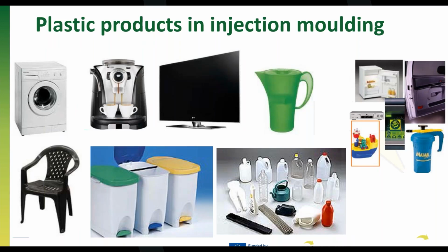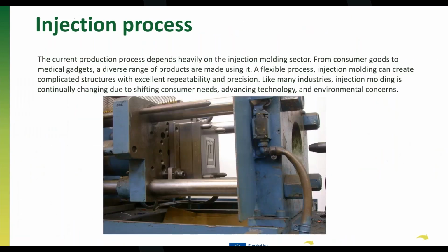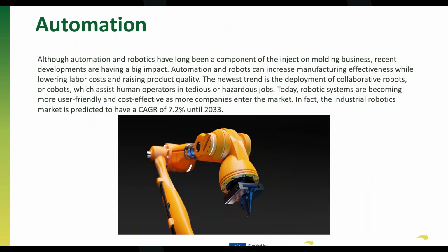In the next slide. The process itself depends heavily on the mold, the manufacturing of the mold, and the capacities that we can have to industrialize and manufacture this flexible mold. So this will be a limitation, as I have already mentioned, and I will keep mentioning it. It's key to manufacture the part, but it's also key to extract the part. This extraction is done in 2 different steps.